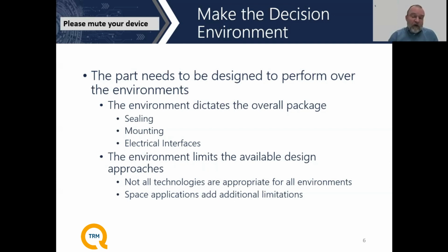So in those environments, not only does it affect the sealing or the venting of these parts, but also the way that the connector launches are done. And sometimes it actually affects the connector selection. If we're coming in with a high power, high altitude part, for example, something that may work at sea level with an SMA connector may very well break down at high altitudes, in which case maybe you have to go up to a TNC connector as opposed to an SMA to mitigate some of those issues. So those are all things that need to be thought of as we're going through the various design choices.